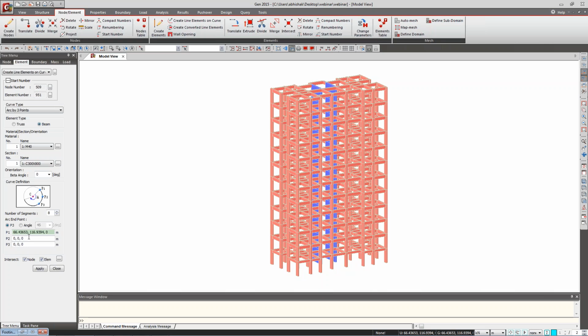No, sir, there is no limit on any opening in the shear wall. It's up to you if you want, and according to that, you have to cross check whether it is a pass or not, how the stresses are coming, and if it fails, then you have to reduce the opening. Mr. Ajit Gokhale sir is asking one more good question: is there any limit on the opening size? No, sir, there is no limit. It's up to you, or maybe a structural point of view. If the member passes, then it is fine. Otherwise, it fails, so you cannot provide more opening space. You have to reduce that opening space, or else you can use only the two columns, and in between you have to generate some beams in this way.